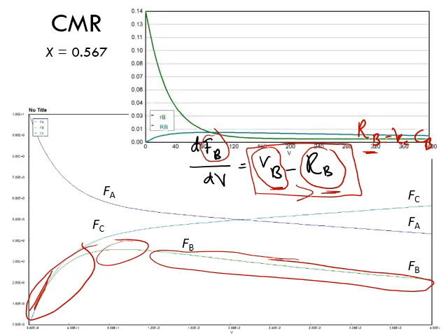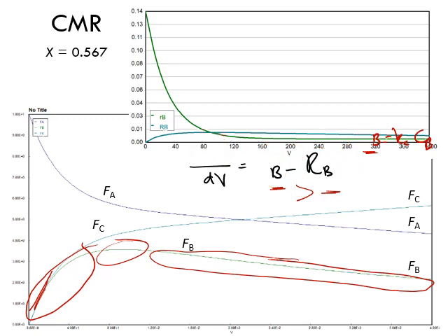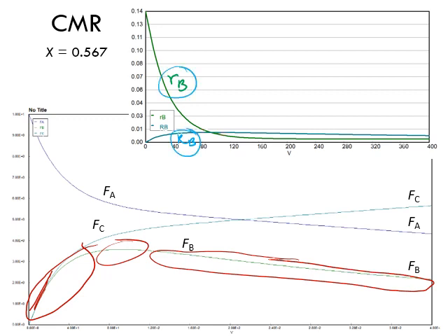So let's plot it and look at it. Let's plot these two variables. Okay, so we are plotting here rB, which is the rate of formation of B, and the other line here is capital RB. At the beginning you can see that rB, the rate of formation of B, is much larger than the rate of diffusion of B. Therefore, FB is increasing. So this happens until it reaches a maximum value. And at this maximum value, actually both rates are equal.